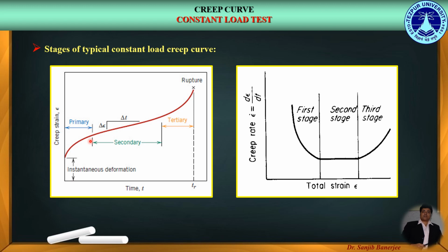Then the creep rate reaches essentially a steady state in which the creep rate changes little with time, and finally the creep rate increases rapidly with time until fracture occurs at this point. Thus, it is natural to discuss the entire creep curve in terms of its three different stages, that is the primary, secondary and tertiary creep.